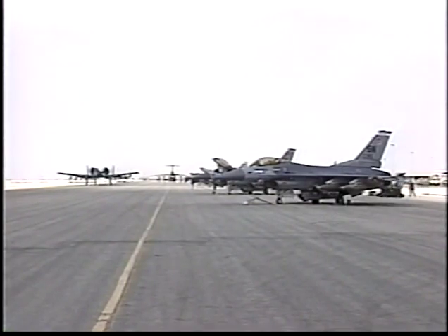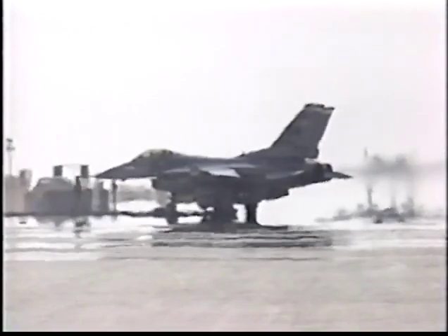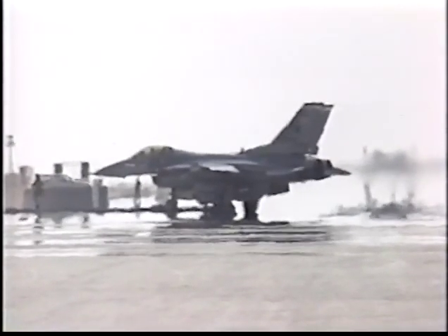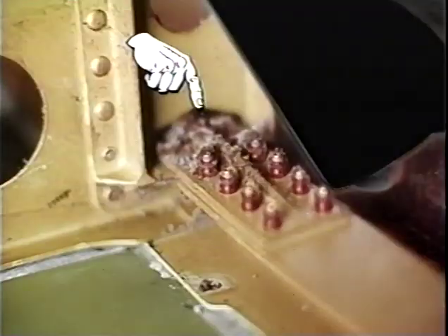Temperatures have a serious impact on aircraft and equipment. Hotter temperatures induce rapid corrosion formation and promote mold and bacteria growth. These biological organisms tend to grow in areas of an aircraft or component that remain damp for long periods of time. Time is an important factor, especially when considering the environment.